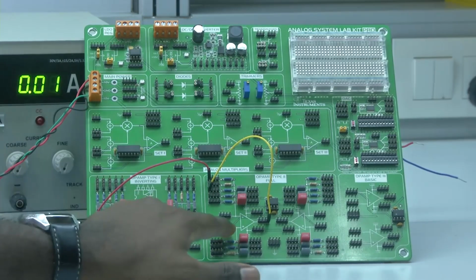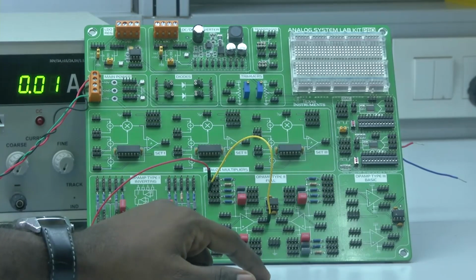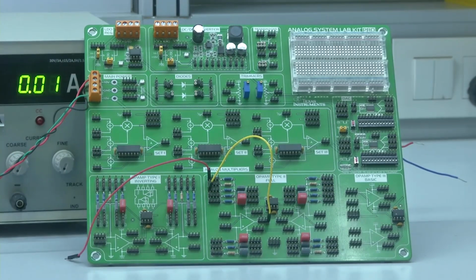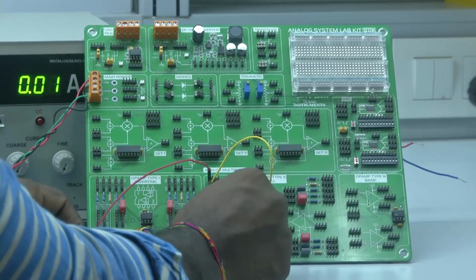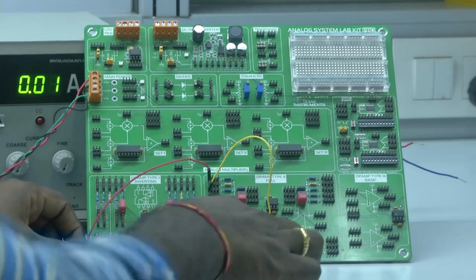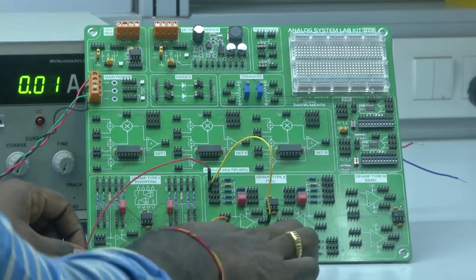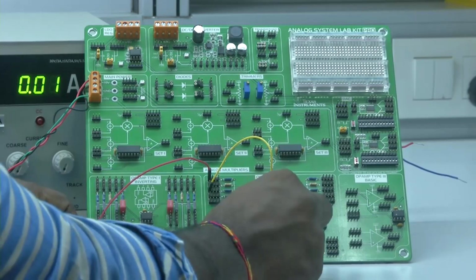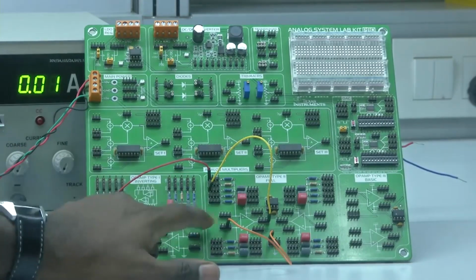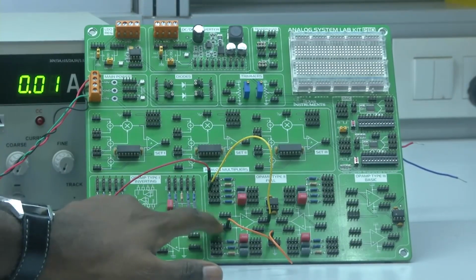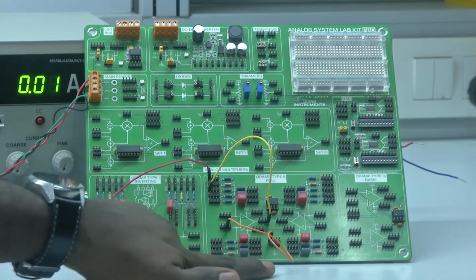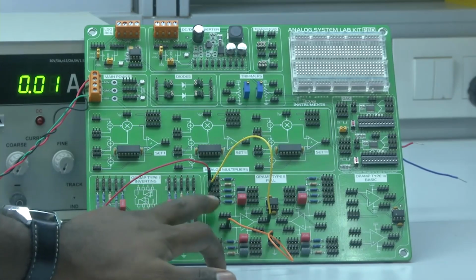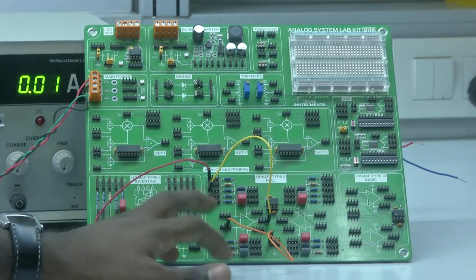But the positive terminal, which is the non-inverting terminal, should be connected to the ground. So, what I will do is take the positive terminal. If you notice, it also has ground banana connectors. So, if I simply connect it between the ground and IN plus, it means the positive terminal is connected to the ground. So, now I have made the connections of the first operational amplifier. Let us see the working of it.